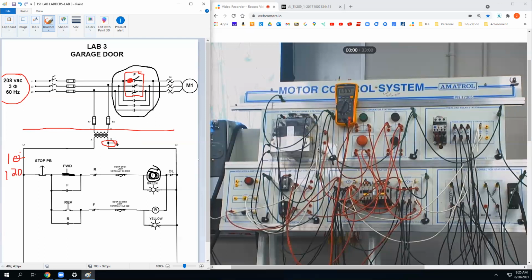Well, remember, ground, your negative lead is going to whatever reference point you're checking to. You're looking for a difference of potential between 2 places. And at any given time in this process, when this whole thing is running, you should know where you should have a difference of potential.